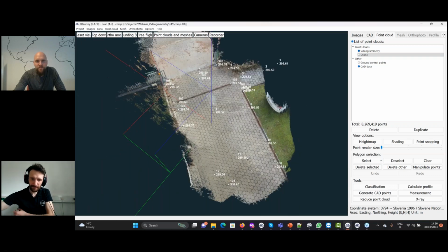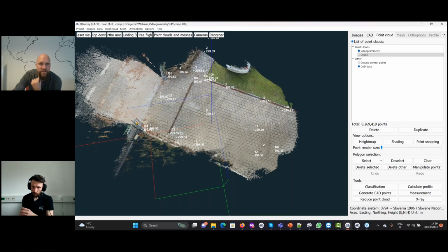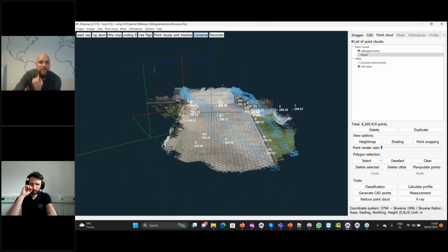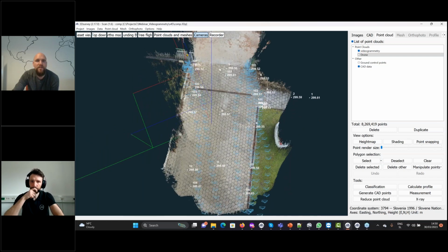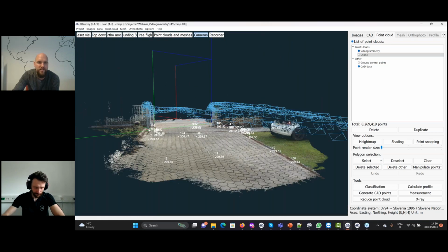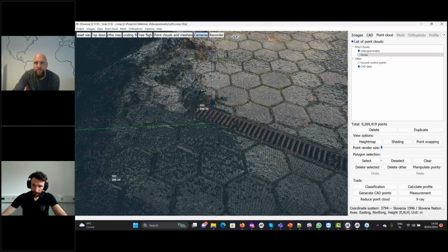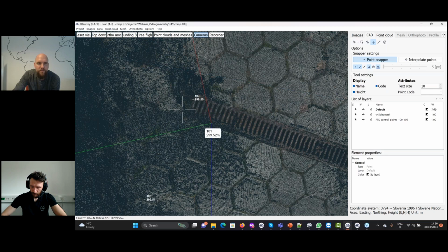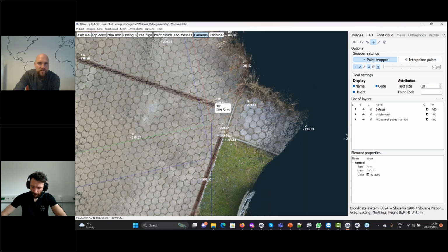So this area here, you see I put a lot of checkpoints in to check it. I just made very fast mapping with videogrammetry, focusing on these two corners. Again, the accuracy that I obtained in this case was pretty high. So here around 2 to 3 centimeters accuracy in elevation. You can see here, I measured the point here with GPS, and there is in photogrammetry.